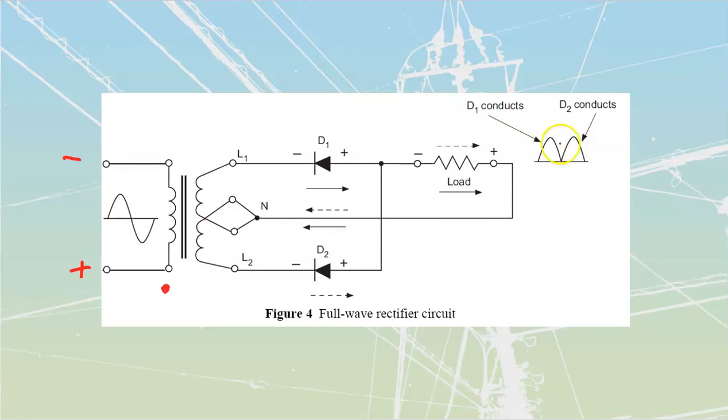Over here they're showing us, diode 1 conducts, diode 2 conducts. Diode 1 would then conduct, diode 2 would conduct. They would alternate as they go through here. If you were to reverse either one of these diodes, you do run into massive problems. Like if I stick this one over here like that, that would mean that at any point where my transformer is positive, negative, positive, negative like that, I would have both of these diodes forward biased, and so I can get current that would then travel through like that. We would end up with a direct short circuit. What we're seeing on these is always, always, always that those diodes are facing in towards that little transformer that we are going to have.